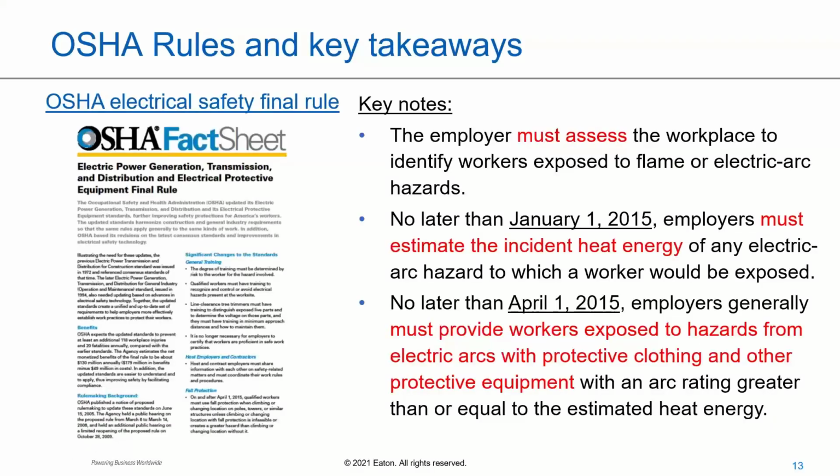Okay, so in terms of arc flash zones, the rule generally is that if you have some type of equipment, whether it's transformer secondary or a piece of low voltage equipment that has more than 40 calories per centimeter squared, it must be de-energized, and you are not permitted to work on that per OSHA. And honestly, I would say no one really wants to work on that.